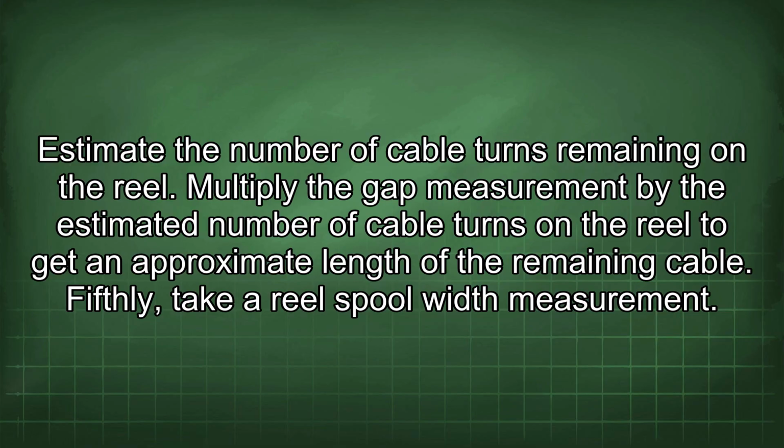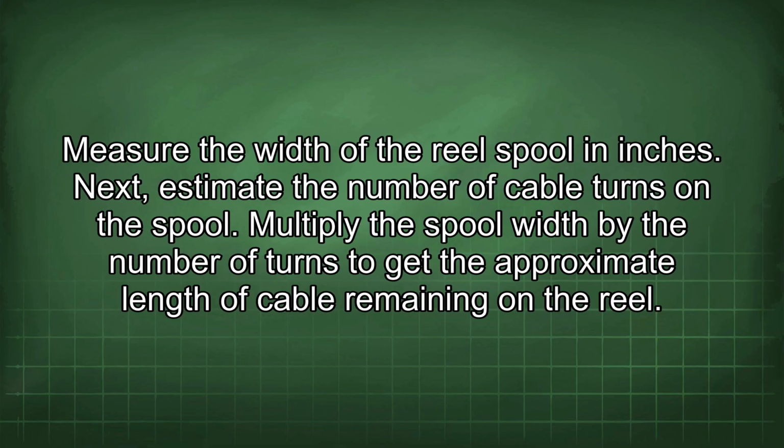Fifthly, take a reel spool width measurement. Measure the width of the reel spool in inches. Next, estimate the number of cable turns on the spool. Multiply the spool width by the number of turns to get the approximate length of cable remaining on the reel.